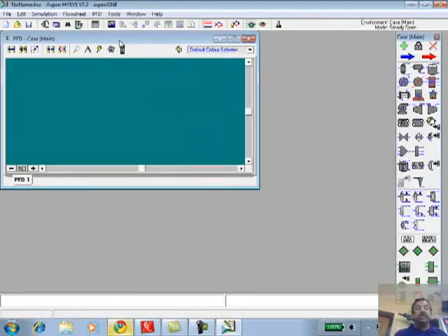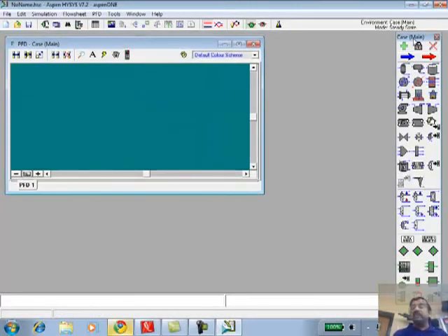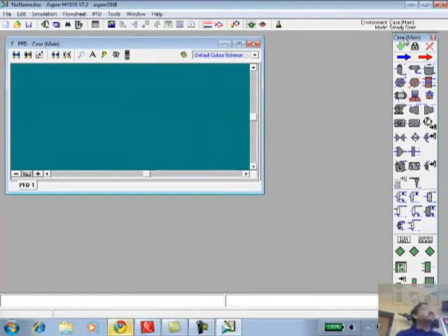So I get this window, and I get another window here, and this is where the power of HYSYS Aspen simulators exists. If you take the cursor close to each one of these icons, you will see it's a separator. Here you have a 3-phase separator, if you have water, oil, and gas, for example. You have a storage tank, you have a cooler, heater, heat exchanger. You will see the theory behind each one of these, the models behind each one of these, in the courses that you are going to see in the future.